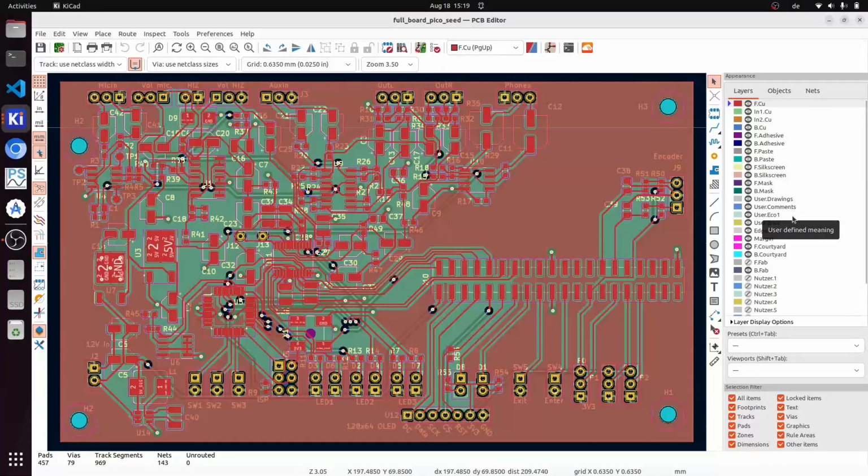using just 2 layers or more. The advantage of 2 layers is that it's still debuggable, it's still correctable, but I found out that it's pretty difficult to build, and also I would need to split ground planes quite a bit, and I've read that this might also cause problems, and one principle which should be followed is to have a ground plane which doesn't have too many cuts. So I decided to build it using 3 layers.